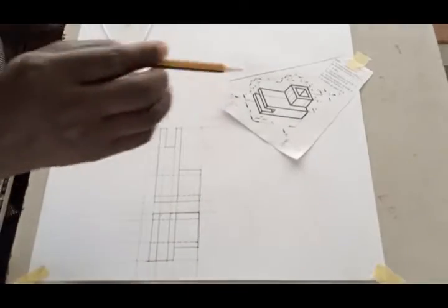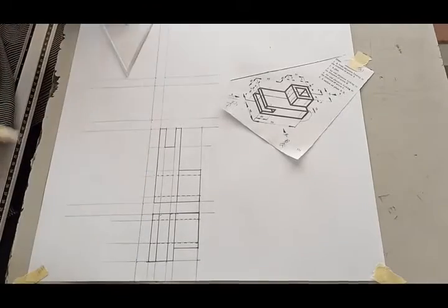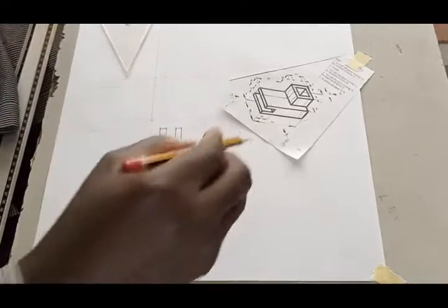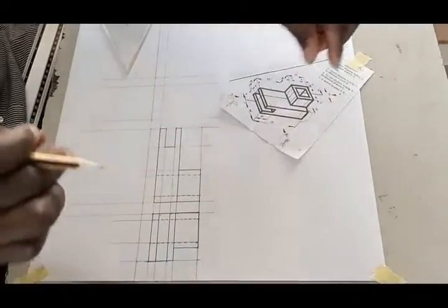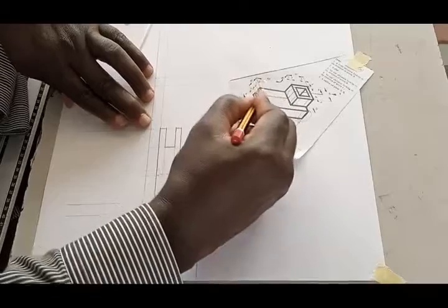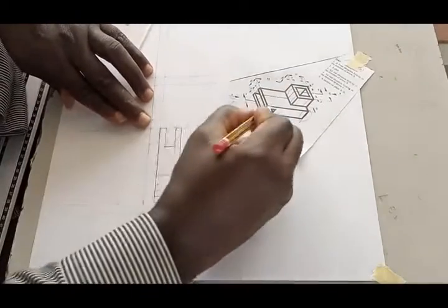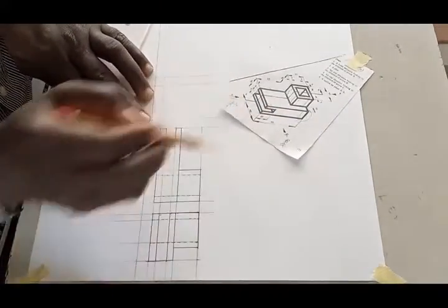Now, the next one is the plan. The plan will be placed under the front elevation. What is the width of the plan? Now, if you want to look at the plan, you have to come back to this thing. You assume you are standing here and you are higher, viewing it from the top. So this box will be by the far end, the top end along this line. That is this line, and this line will fall on this one, whereas this one will fall on the bottom, and the width is 40.